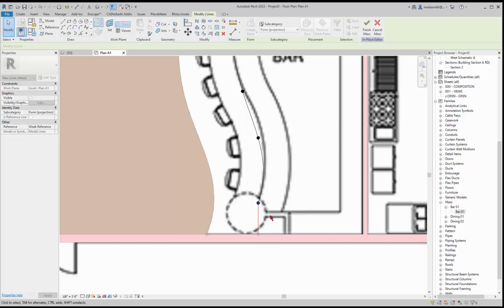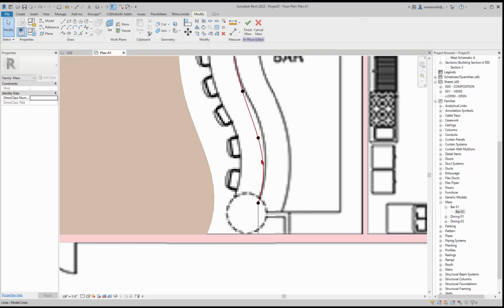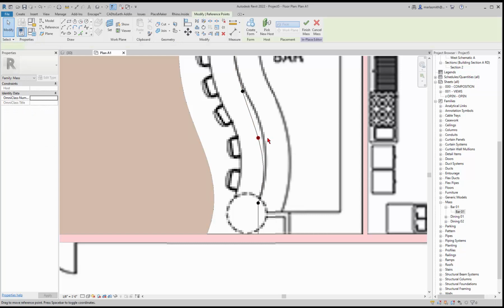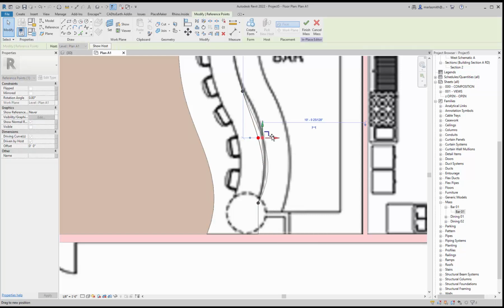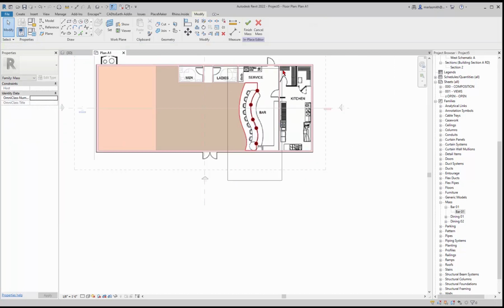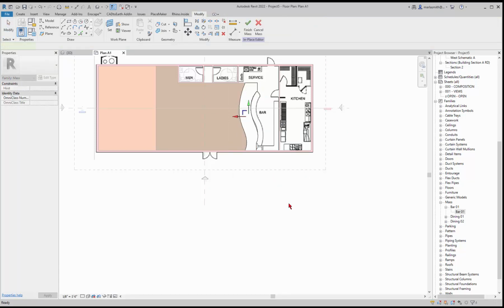Like if you move this guy up to there, the straight line up, it will actually move that one, and then you can kind of adjust these. So, again, it doesn't have to be exact, but get it kind of close. That looks pretty good. And then I just need to select them all and create form, right? And it'll let me create that 3D form.